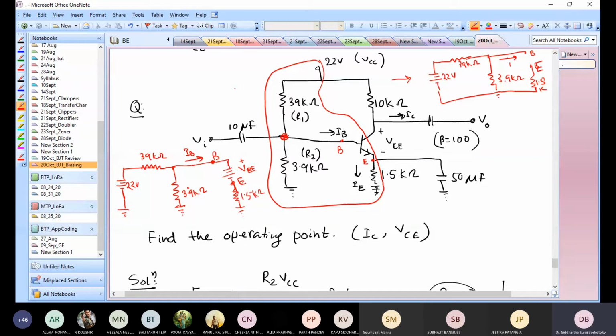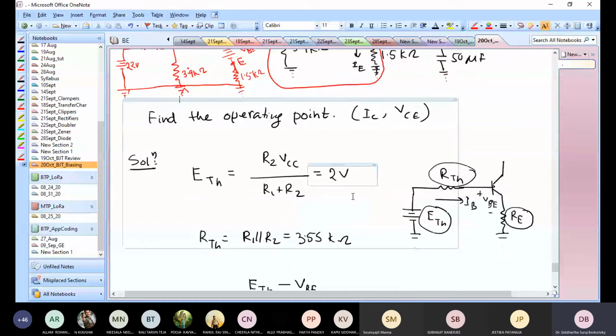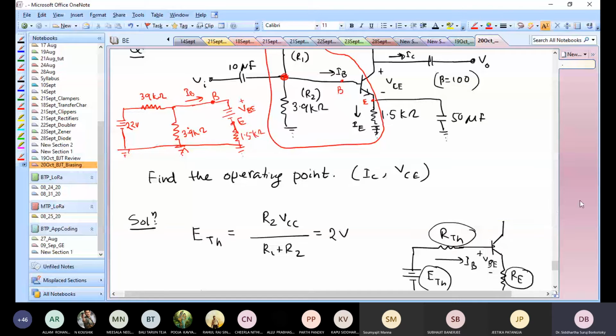Fine. So now I have a very easy to solve circuit. I'll just connect it this way, so it looks like exactly the kind of circuits I'm more familiar with. So this is the circuit. It's a standard circuit. So my question is, given this circuit, what is IB? That is super simple to find out actually. And how do we do it? You could solve it any way you want. But in our theoretical discussion, we discussed that we would do it using the Thevenin equivalent. Because I want IB, I would just determine the Thevenin equivalent of this part.